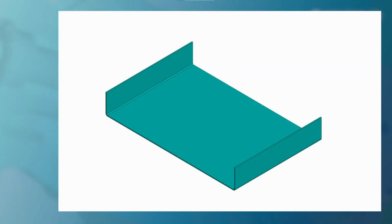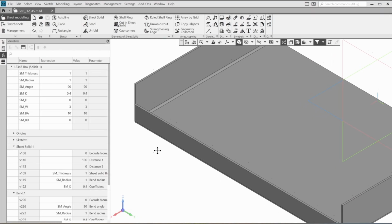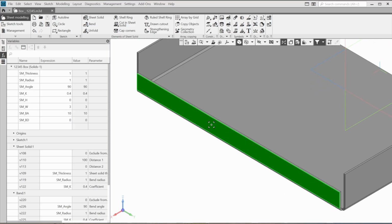Now we'll create these 3 bends. Pay attention, the bend corners are cut at 45 degrees. And then we'll adjust the shape of the lateral sides. Let's edit this bend. Double-click it.